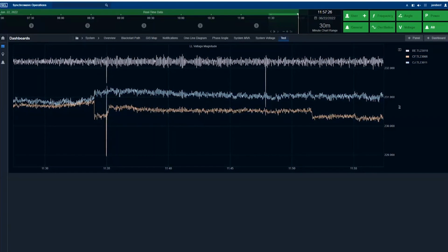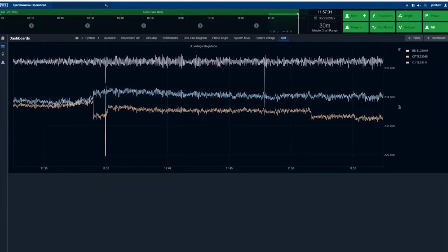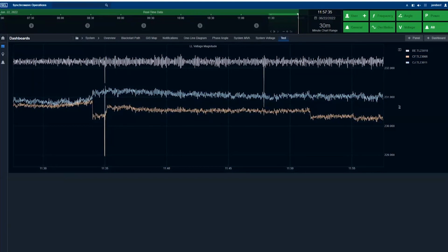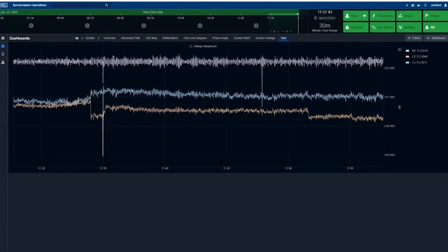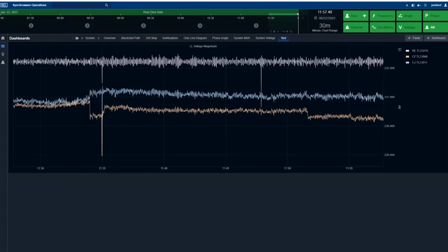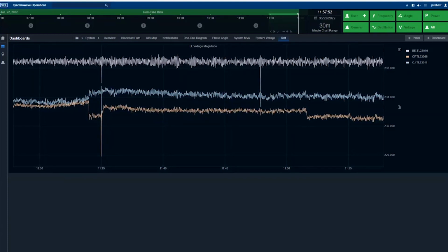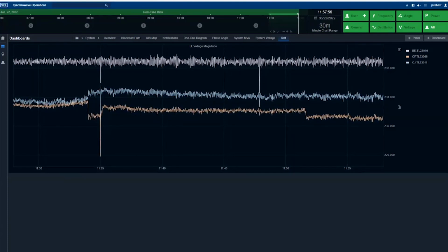So I'd say there's kind of 3 tiers that we have. The first tier that I would recommend is that you install a PMU to at least monitor the bus voltages at each of your points of interconnection. So if you have a substation that's at a point of interconnection, whether you're a microgrid installation, you want to measure that interconnection, or if you're a utility and you're interconnecting with neighbors, definitely want to have your interconnection points monitored.